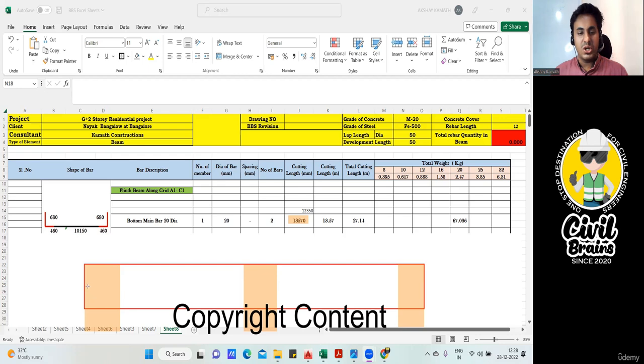You'll start your development length from here, this green color. I'll take the red only, just to visualize the same thing. Your development length will start from here, up to here is your development length. After that, it is your straight portion of the bar, which was black in color.